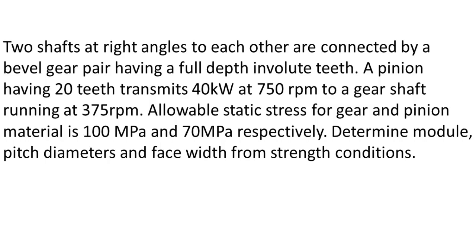Strength conditions means we are going to only use the beam strength equation. We are not going to use the wear strength equation because they have clearly mentioned you have to calculate only on the basis of the strength conditions, meaning the beam strength condition you have to use.